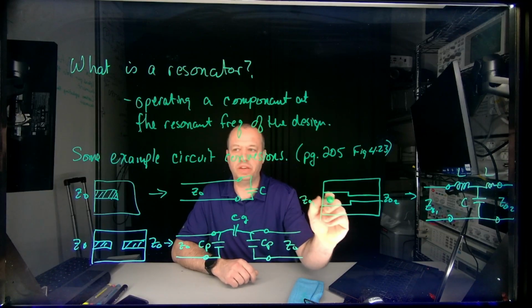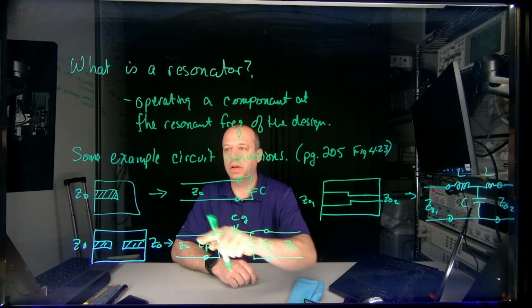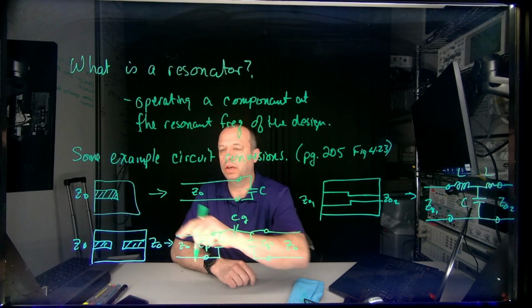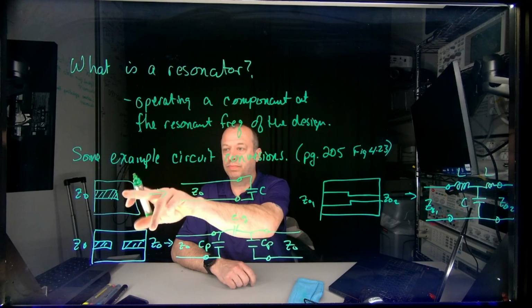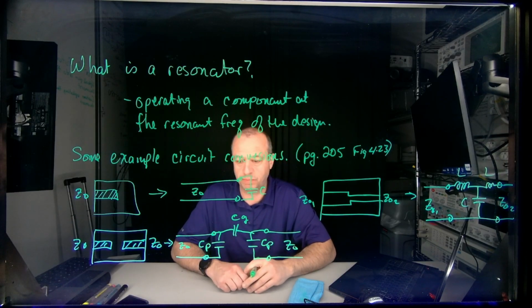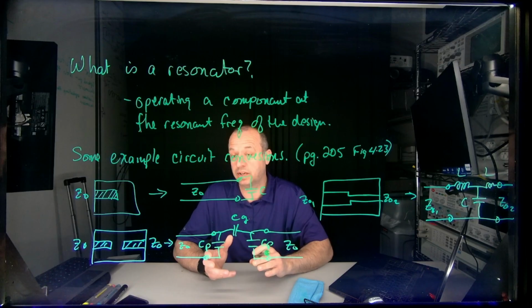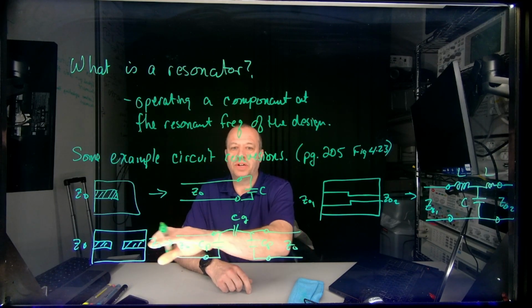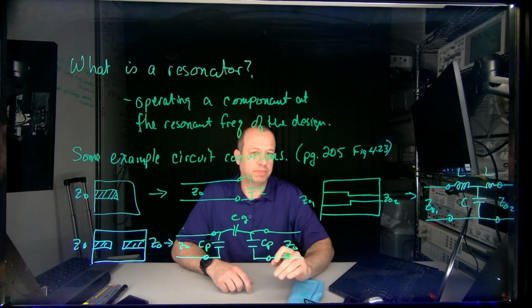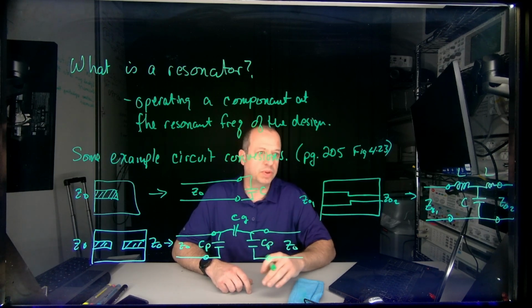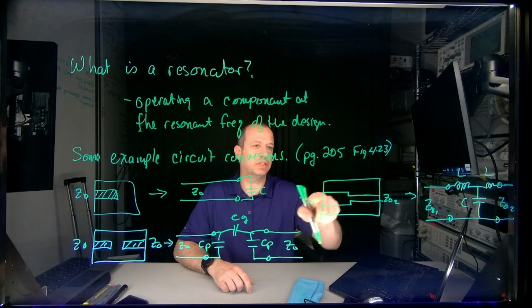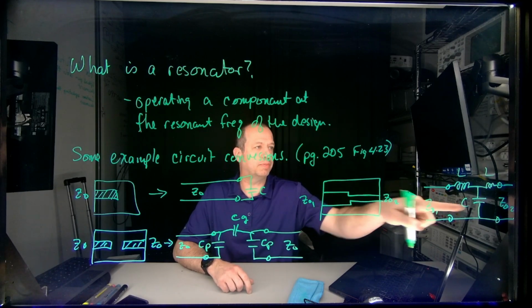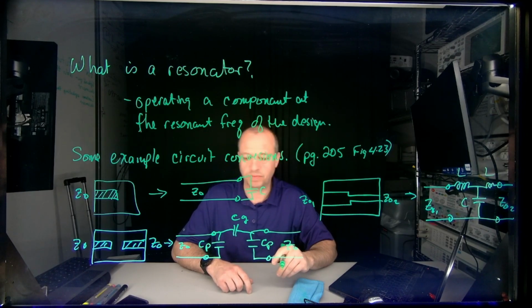We will see these more often. This is essentially a symbol, or your first one is an example of kind of like a trace patch antenna. But it turns out to be a capacitor. We have our other capacitor, we have our stepped impedance. So this is what happens when we do stepped impedance. As you can see, when we do this sharp step, that's really where these capacitors come from.